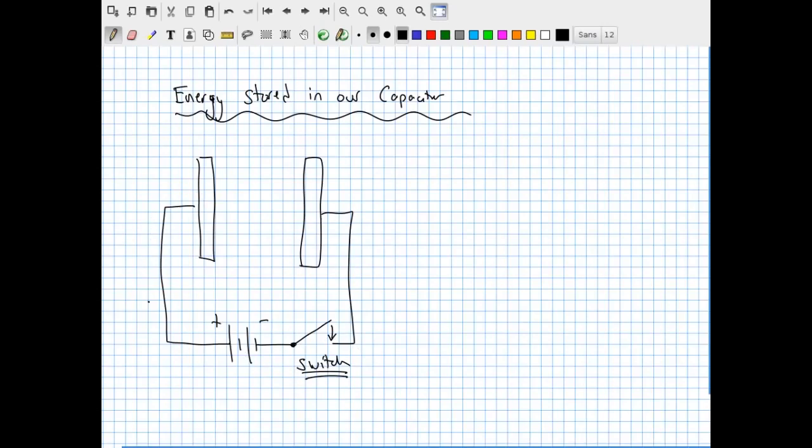I could begin to move electrons from the left plate over to the right plate, and thus cause a positive charge to pile up over here and a negative charge to pile up over here. And because I have some potential from the battery, I eventually expect, given enough time, that the same potential difference will occur between my plates, and the movement of charge will simply stop, because there is no more net electric field inside of the circuit.